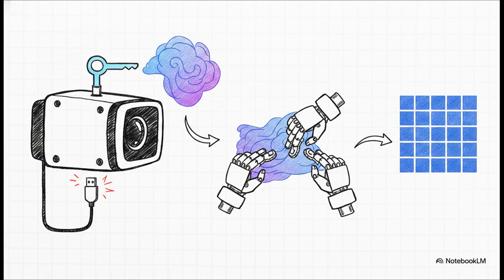Standard OpenCV video capture just doesn't have the flexibility for uncommon proprietary APIs. A lot of high-end camera manufacturers don't use standard USB UVC interfaces. Standard USB is plug-and-play, like your laptop camera, but industrial gear is a whole different beast. The fix? You literally have to bypass standard commands and use the manufacturer's provided API or SDK. You capture the video directly into a raw memory buffer using their SDK, and then manually mold that buffer into an OpenCV Mat object so your pipeline can finally do its job.